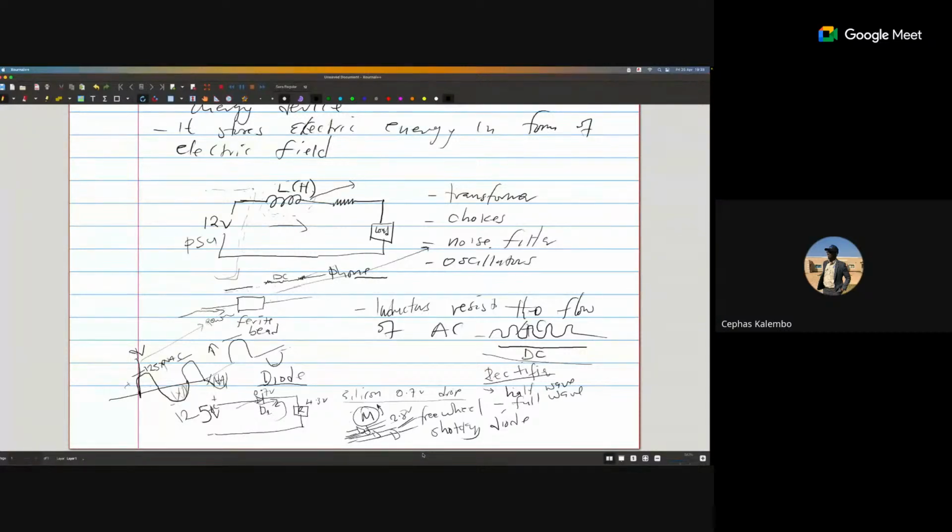Yes, it's okay. A diode can be used as a basic voltage dropper. You can use a diode to drop the voltage, but it's not a precise solution. I have seen even professional products that you buy from the shops where they have used a diode to drop the voltage. The advantage is that the circuit will be a bit efficient. The key word there is a bit.